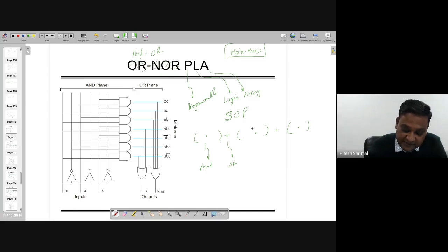Right? So in that case, pre-programmed logic is given here for the case of sum and carry. We know the equation, right? So sum and carry are made with the combination of different inputs, and you can write this down and find this out, right? And for this one, it's AB plus BC plus CA.